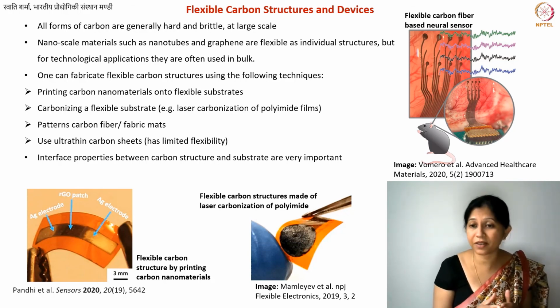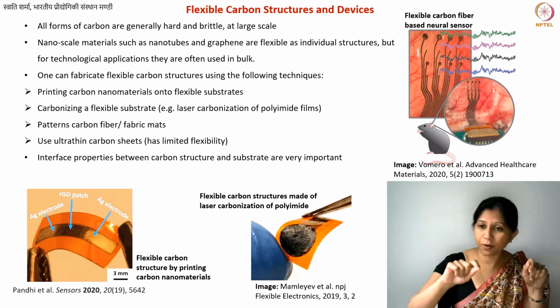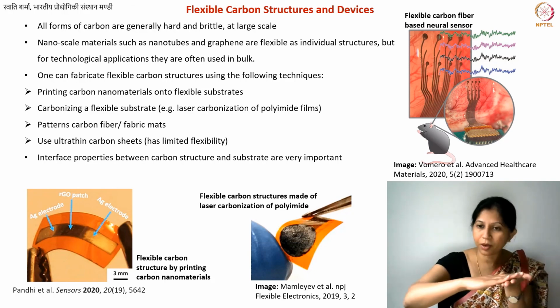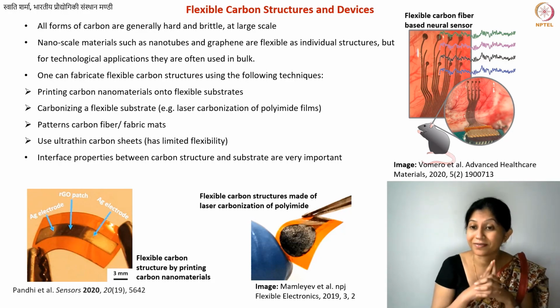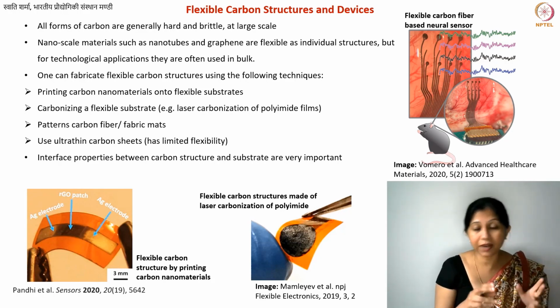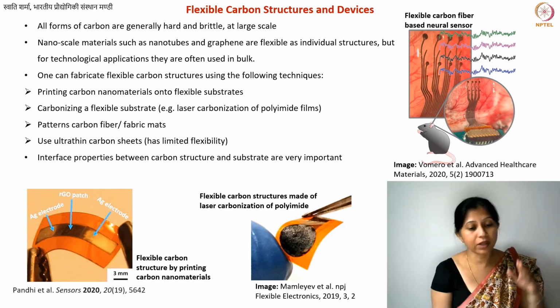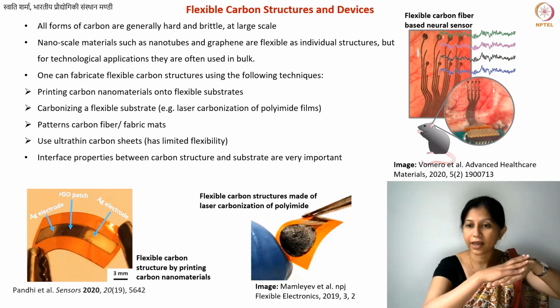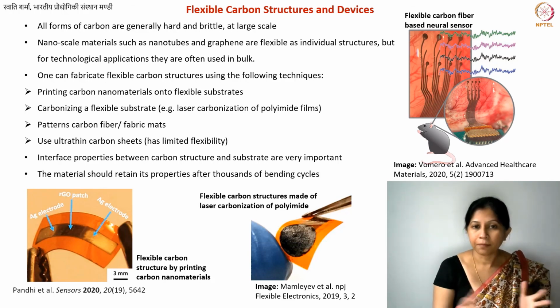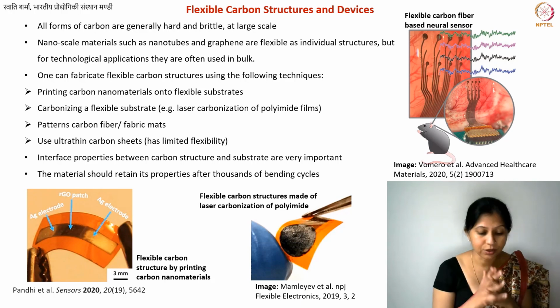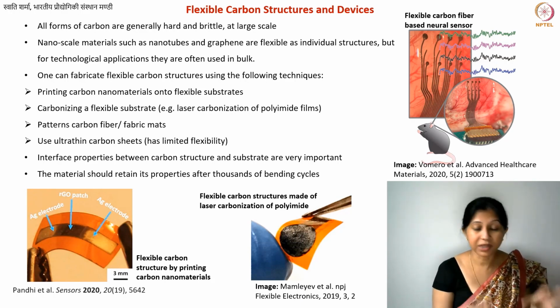And of course, the interface properties of these, even when you're performing printing. So even when you're performing printing, this film-like structure should not peel off. So this peeling off from the substrate is also one of the challenges. Here, when I'm talking about interface, it's about the interface between the substrate and the patterned structure. So this is an important thing. And as I said, thousands of bending cycles you need to evaluate before you can think of using this material for a regular application.